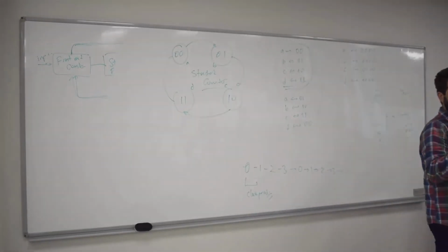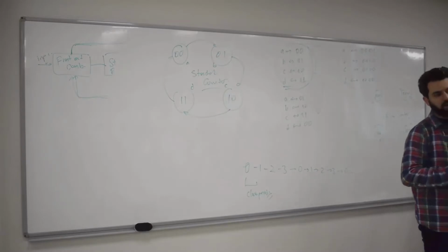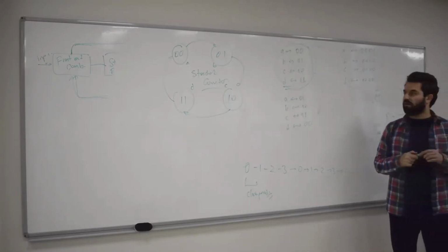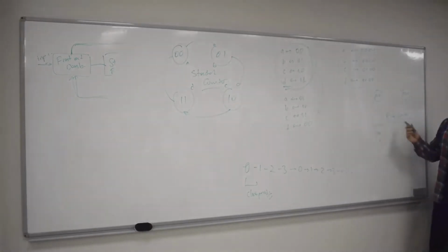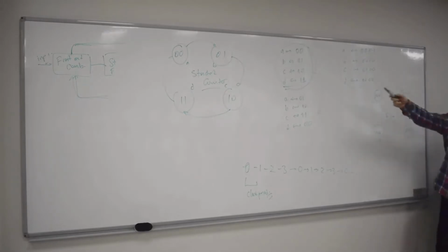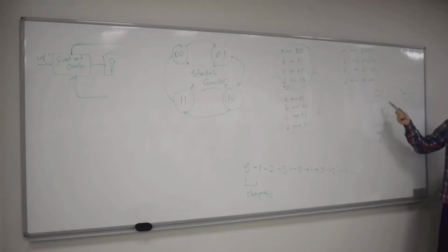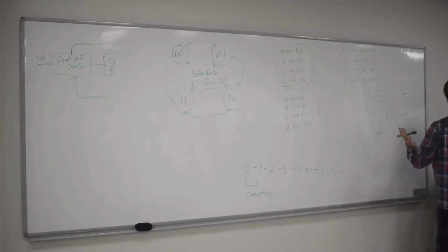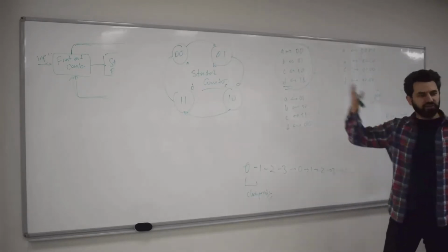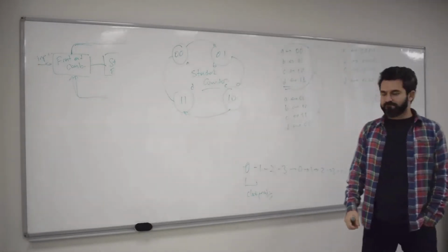We've got a question? Yes. Go ahead. What's the difference between the standard counter and the ring counter? This one has 4 flip-flops, 4 states, and that one has 2 flip-flops. I'm sorry, 4 states in both, but you use 4 flip-flops to represent the state in one, and 2 flip-flops to design that circuit in the other. And because of that, the ring counter doesn't have any front end or back end. It doesn't use any gates, okay? It's just an empty front end and empty back end in that general description, okay?